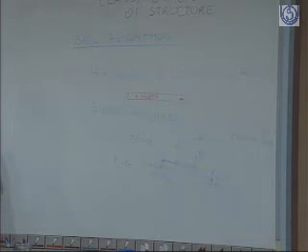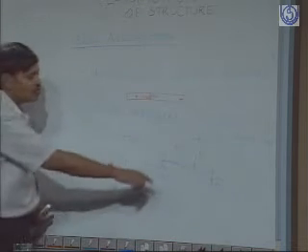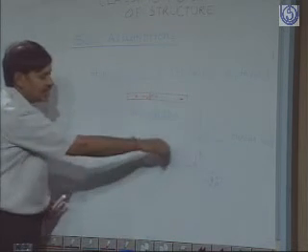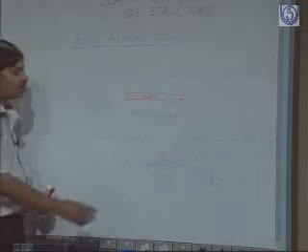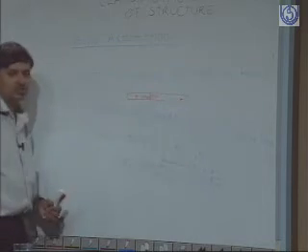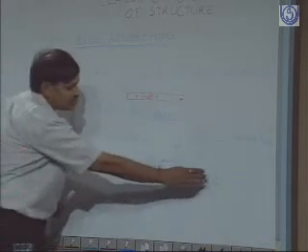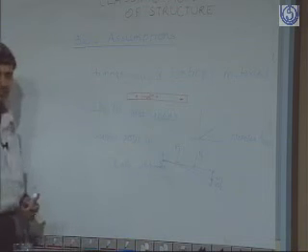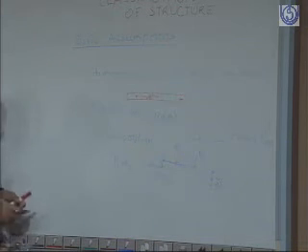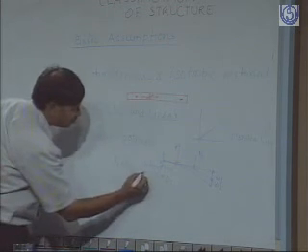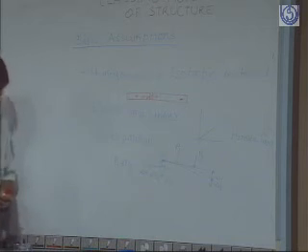It is irrespective of the order in which you apply the load. You may apply the load P2 first and then P1 afterwards, or you may apply both the loads together. The deformation will be the same, delta 1 plus delta 2. So, this is the principle of superposition.